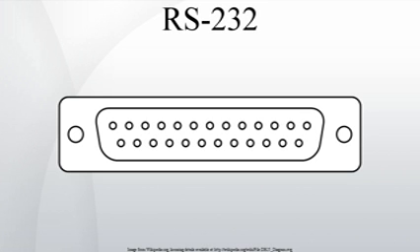No method is specified for sending power to a device. While a small amount of current can be extracted from the DTR and RTS lines, this is only suitable for low-power devices such as mice. The 25-way connector recommended in the standard is large compared to current practice.